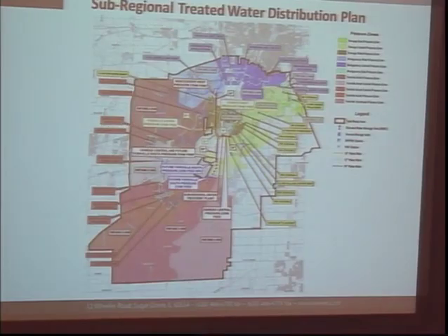Next exhibit then is how, once the water is treated, will it be transmitted back to each one of the communities? So as mentioned, you have 3 pressure zones across your community. Yorkville has 4 and Oswego has 3. Well, when we pump this water out to a zone or a portion of a system, it has to meet the hydraulics of that zone.